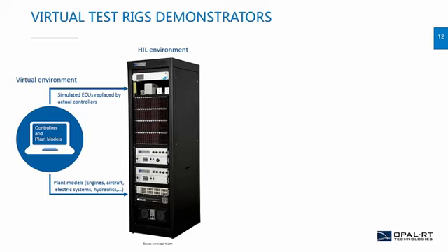This setup is what we refer to as a hardware-in-the-loop environment, and it involves the simulation execution in real time in order to interact properly with the actual controllers. To this setup, we can also add devices such as fault insertion boxes or mapping boxes in order to condition some signals.